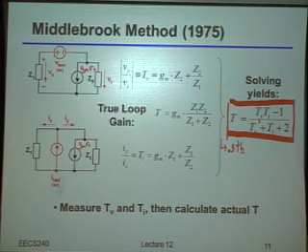If you take two big numbers and multiply them and then subtract another number and the end result ends up being something very, very small, you have to be worried about the numerical accuracy of the simulator. Because you can get some very big errors anytime you have those kinds of situations, if internally under the hood things are not handled very carefully.